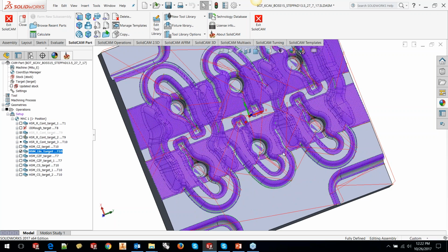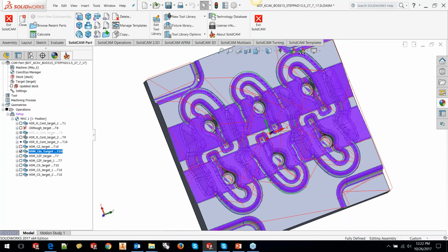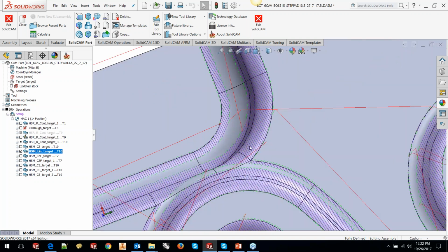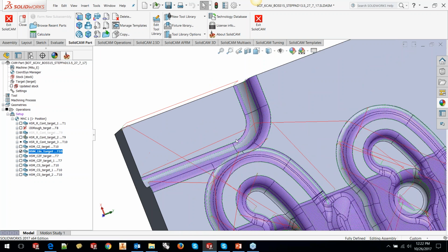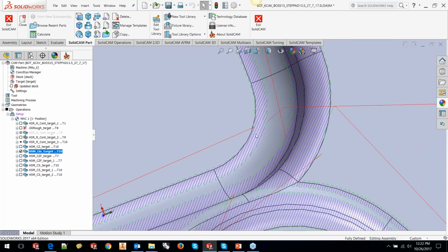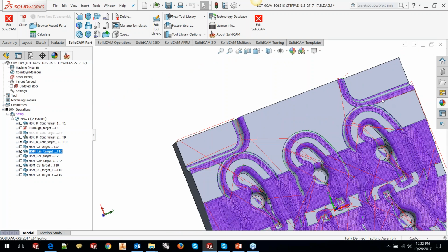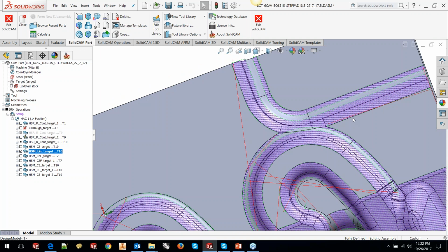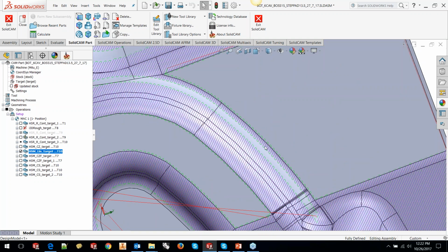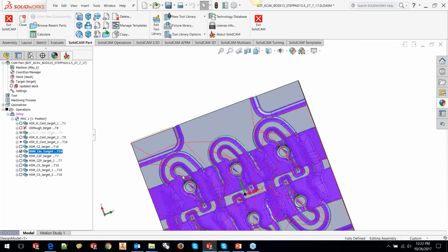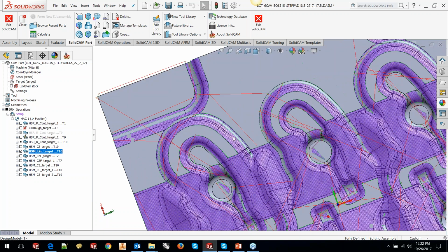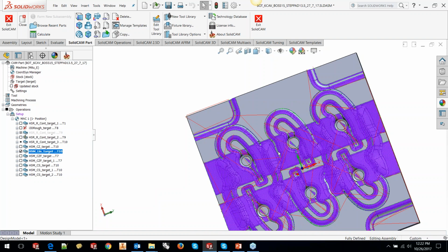It's a process limitation, and you can see that it's machining this fillet, it's machining a small portion of the fillet here. Okay, it's doing a lot of unnecessary things that I don't want it to do. For example, it's also doing this one halfway here. That's because of the slope angle. Okay, these things, especially in linear machining, can add quite a lot of time into your machining time. It can eat away your machining time.